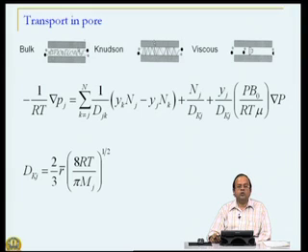Now, bulk diffusion arises because of molecule to molecule contact. Now, in a reactor, for example, whose dimensions are in meters, bulk diffusion is the dominant phenomenon. However, when it comes to a pore, because the size of a pore is small, there are several other ways which also drive the reactant through the pore.